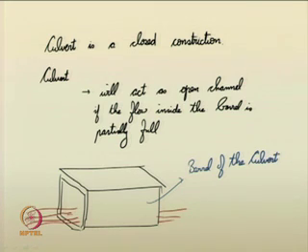So, if the barrel of the culvert is full, if the entire water is full like this from here inside, then the culvert will not act as an open channel, means you cannot call the flow inside the culvert as an open channel flow, you have some constrictions there.